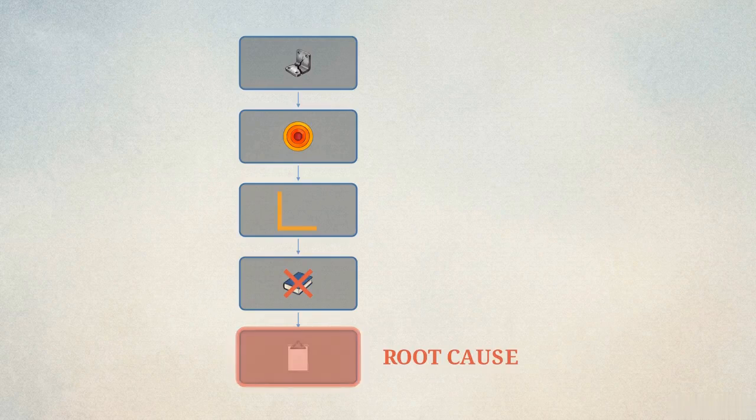This vertical 5Y flowchart allows us to drill straight down through the variables we identified. We start with the physical evidence. The bracket cracked due to a high stress concentration, and that was caused by a sharp 2 mm bend radius. Pause the video and trace the final 2 steps yourself. What systemic flaw would allow a sharp bend radius to reach production? The engineer used an outdated design standard because the company lacked a mandatory design review checklist.